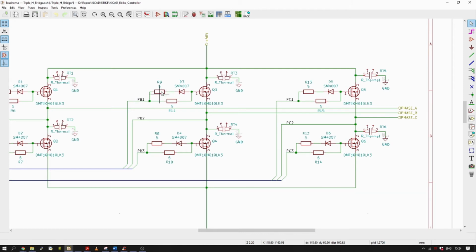It looks a little bit different to what we saw, but really there isn't anything different here. So in order to turn on this MOSFET, the gate driver IC would provide current here. It's obviously blocked by this diode, so it has to go this way through. This just allows you to have different turn on and turn off gate resistors. So that's quite a good way of having maybe a slower turn on but a faster turn off. In actuality, both of these are 5 ohms for me, but you can change it to different ones should you wish. So that's just a little bit there.